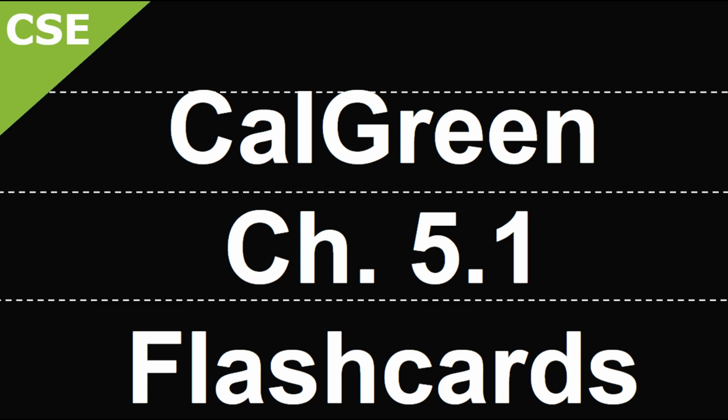A table is provided in CBC Chapter 11B 228.3 with the following columns. The first column provides for the total number of EVCS facilities. So first you would figure out the number of electric vehicle charging stations from CalGreen code, then come to this table in Chapter 11B. And if you have 1 to 4 electric vehicle charging facilities, then you read across the row and it says you need to provide 1 van accessible. So one of those EVCSs must be van accessible. However, 0 of those need to be standard accessible and 0 need to be ambulatory accessible.